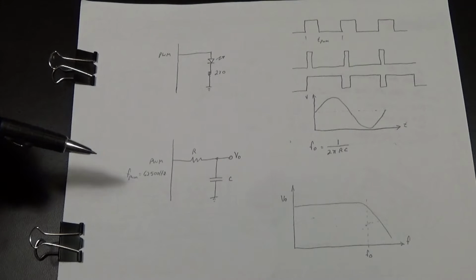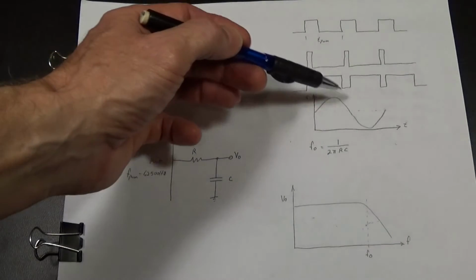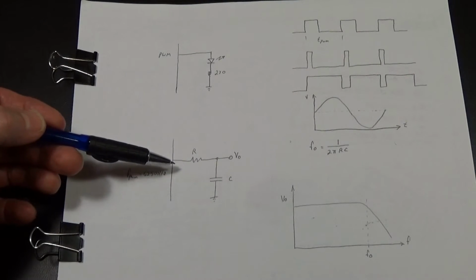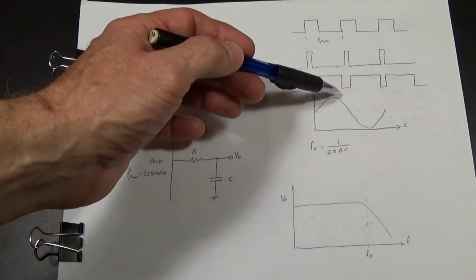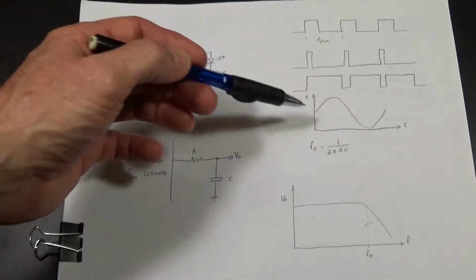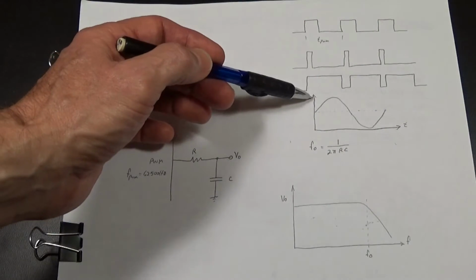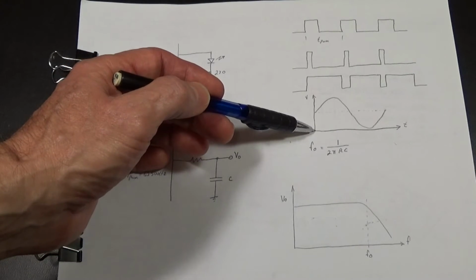And then I showed you how to create a sine wave like this by outputting different values to the PWM to change the duty cycle, so that the duty cycle represented the different voltage levels as the sine wave goes from 0 to the maximum. In this case, with the microcontroller I'm using, this would be 5 volts, and this would be 0 volts down here.